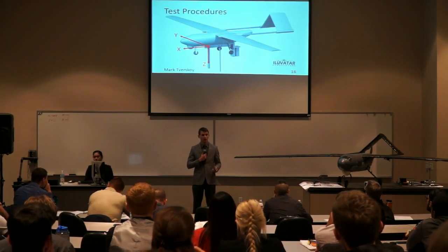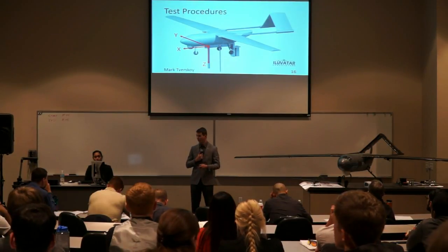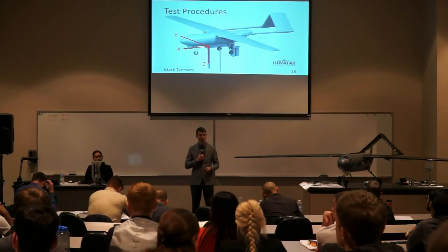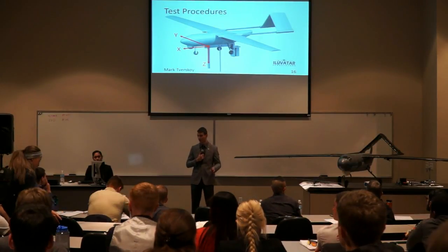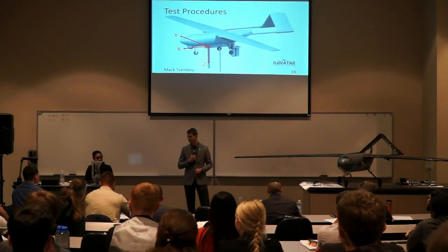The LabVIEW acquisition code used a coordinate system that was based around the front screw of the balance, with a standard stability and control axis, with the x-axis going out the front, the y going out the right wing, and the z-axis pointing downwards.